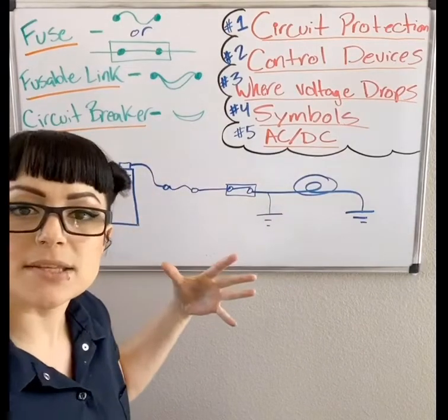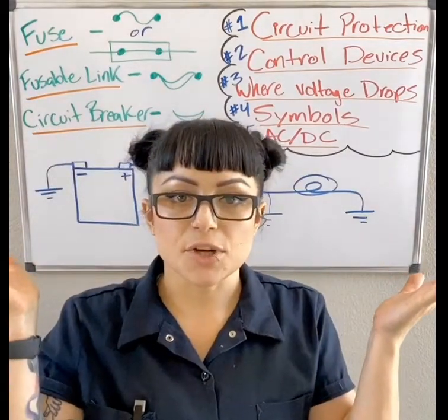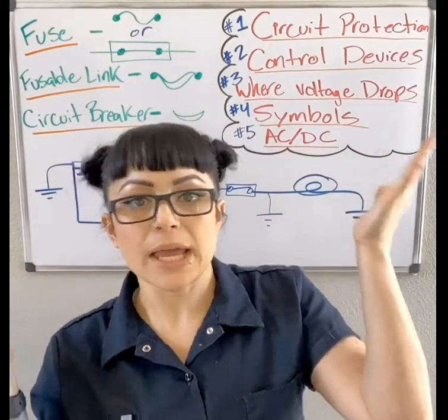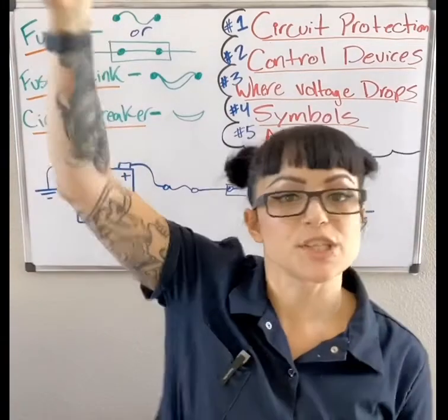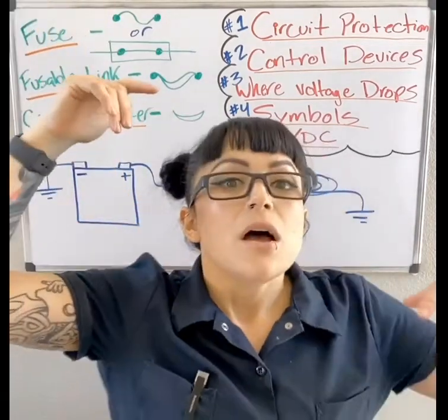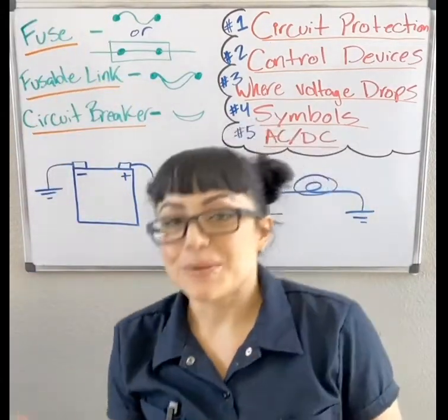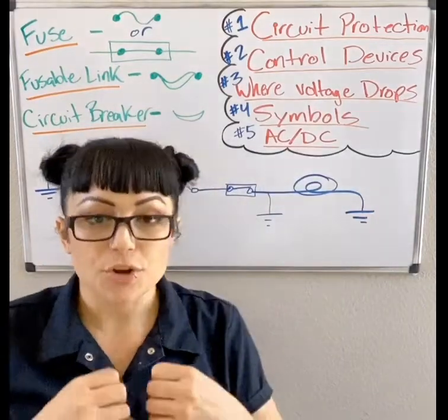But the problem is what have we done with the resistance in the circuit? It went from high to nothing, or very, very little. And so amperage is going to spike up like crazy. Well, without any circuit protection, it would create a fire.